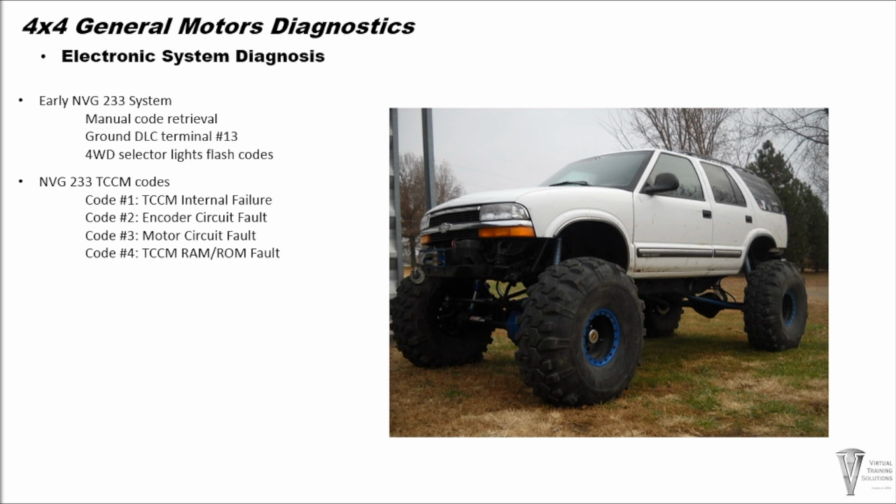All NV233 transfer case codes are single-digit codes. These codes are: code number 1, Transfer Case Control Module internal failure; code number 2, encoder circuit failure; code number 3, motor circuit failure; and code number 4, Transfer Case Control Module RAM-ROM failure.